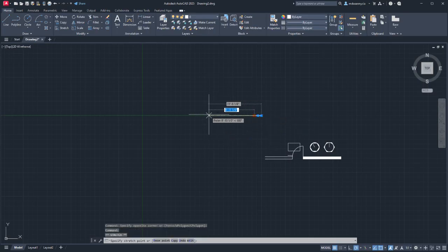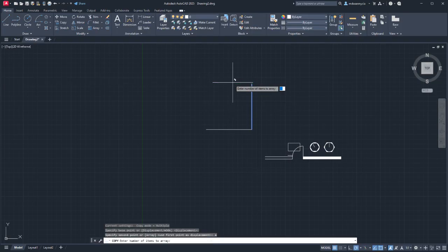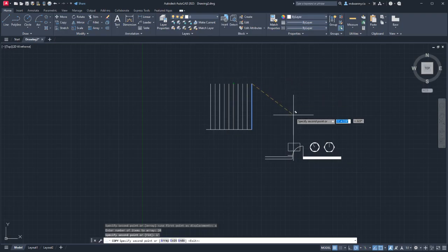with that tool. So for example, if I wanted a grid of 1 foot squares of 10 by 10, I could do 2 lines like this, get my 10 foot, and then we could do copy, move it out, array, 10 items at 1 foot. And then we'd need one more for the end here.